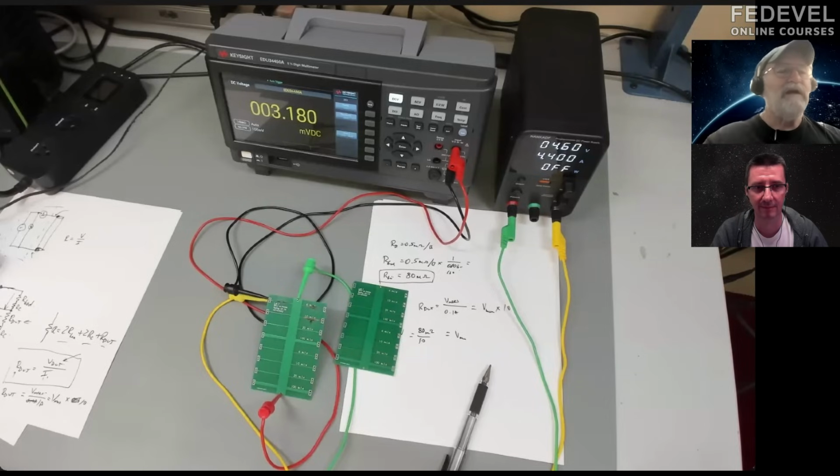it's a question of the sheet resistance, which is still the same. It's still on the order, if it's 1 ounce copper, of half a milliohm per square. And the typical resistance of a via, depending on the dimensions, is on the order of a couple of milliohms. And so most of the resistance is dominated by the vias.